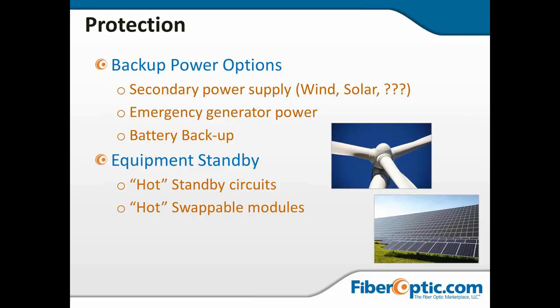And then you want to look at your standby equipment. Are your standby circuits going to be hot? Are you going to have hot swappable modules where you can change out perhaps a DWDM discrete lambda transmitter without having to take down the whole system? Now it's going to be more expensive, so again, it's all going to be a matter of cost and where your price point is.